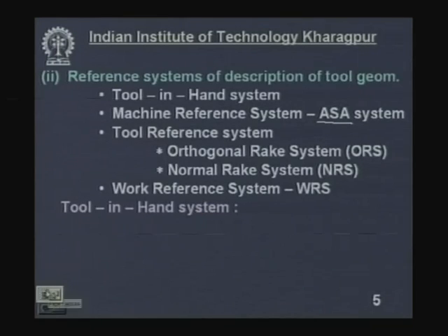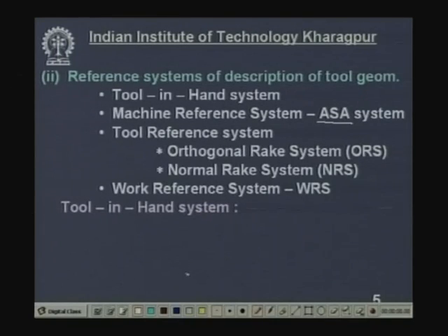Here you cannot describe or specify the angles. For example, say this is the machining operation, this is the cutting tool and this is the workpiece, the turning operation. This is the main cutting edge which removes the chip, this is called auxiliary cutting edge, this is the rake surface of the tool and clearance surface are vertical. Now, this can be shown in this way also in 3D.